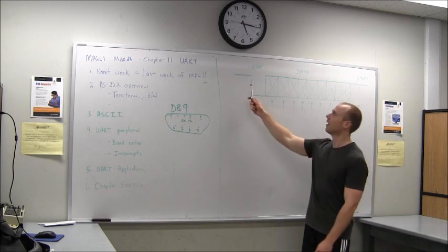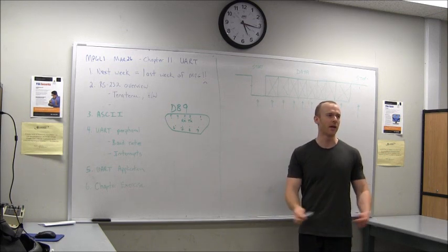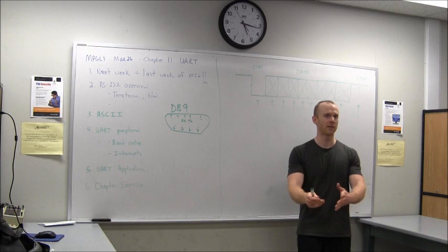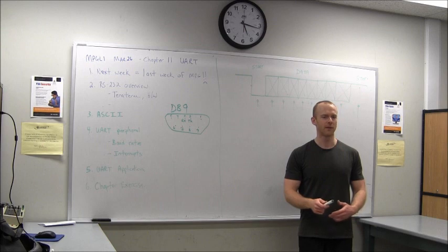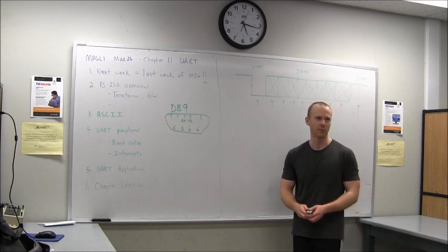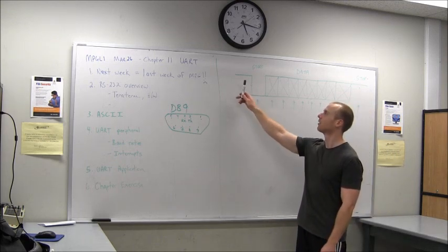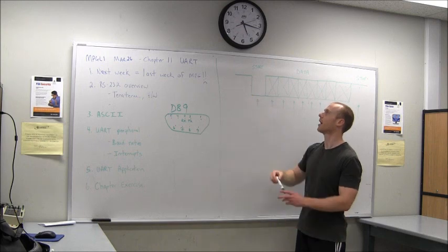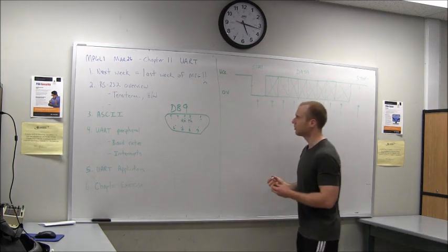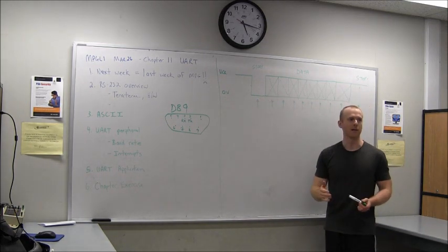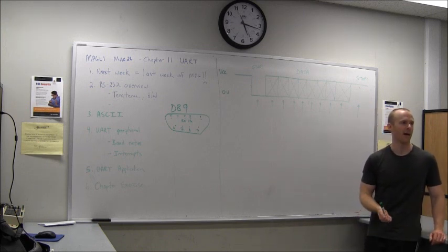For the logical level, if you're just looking at one particular signal line, most of the time in an embedded system, even though you can run full duplex, you let one device talk and another device listens and talks back. So you're exchanging data back and forth separately, sort of like half duplex, even though you have that full duplex capability. But the signaling works the same way for both lines. So you always start in the high state. Considering that this is on the board, you'll be at VCC, which is 3 volts on our system, and that's the idle state.